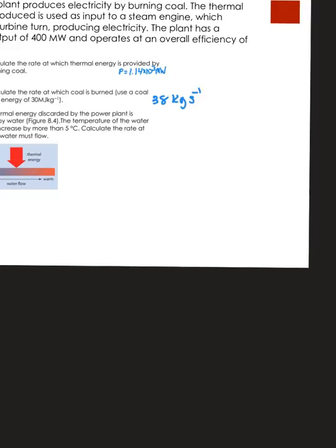Well, we're heating up water again, so let's start with our equation that we know we're going to use for heating up water. Q equals mc delta T. And we're doing rates here, so it's going to be per time and per time. And there's that mass per kilograms that we know we're going to look for. Kilograms per second we know we're going to look for. But what is that Q per T again? That's energy per time, rate of energy. Right, that's power.